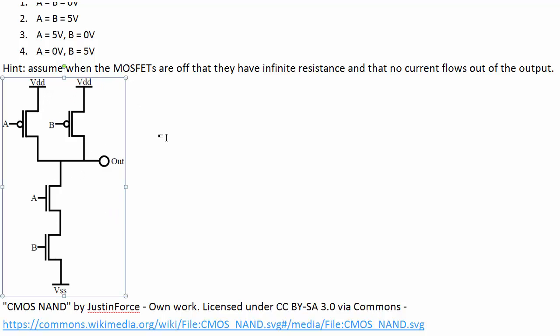So this one thing, being able to build CMOS using MOSFETs, and the fact that we can build MOSFETs really small, is what allows us to make computer chips that don't just blow up from the amount of heat they're putting out. We can have billions of transistors in a computer chip and be operating all of them at decent voltage because there's very, very little current going through them.